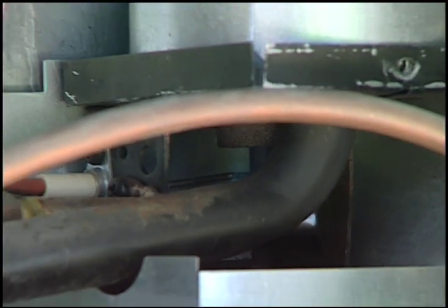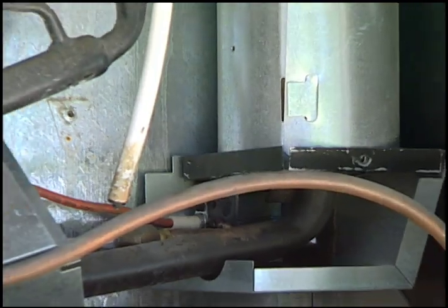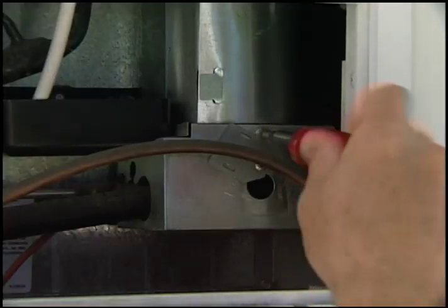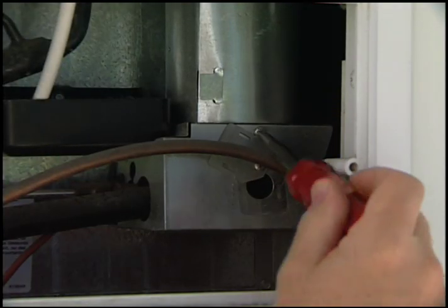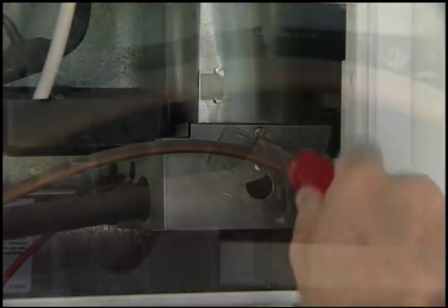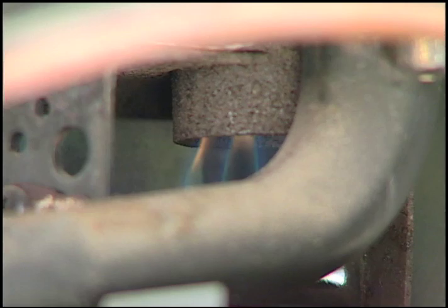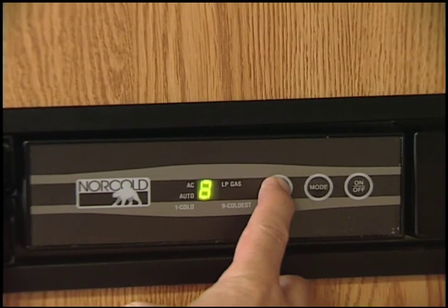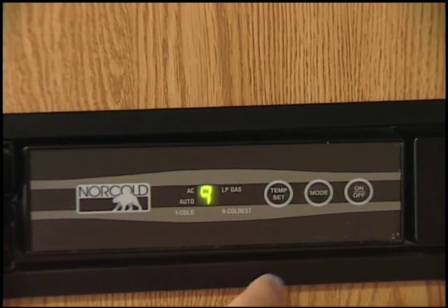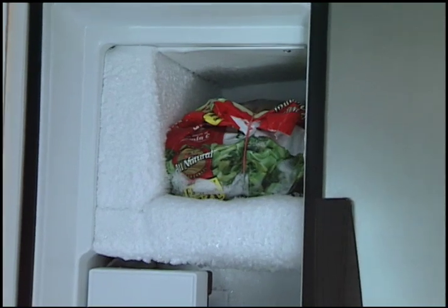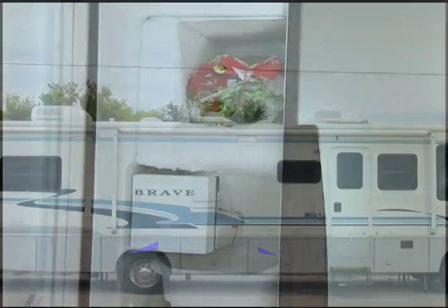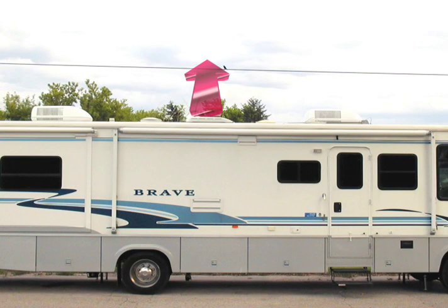If the flame blows out under especially windy conditions, try to position the RV to avoid the wind blowing against the wall vents. Make sure the metal shield is around the burner box and secure. Confirm the burner and flame are adjusted correctly. If the problem persists, set the temperature to max. This measure can only be temporary because after a few hours, items in the refrigerator compartment will freeze. Do not cover the vents to prevent flame blowout. Circulation of the air is necessary for proper and safe operation.